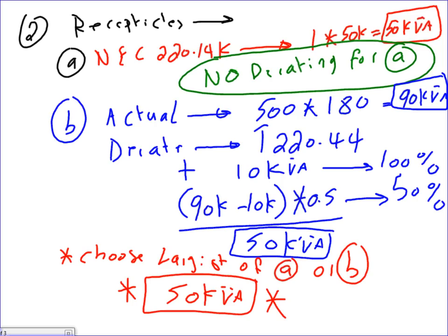But Mike Holt says in his book, for multi-outlet assembly, you multiply, if it's non-simultaneous or simultaneous, 180 VA for every 5 feet if it's non-simultaneously used, or 180 VA for every 1 foot if it's simultaneously used. But I can't emphasize enough, you're going to add them right in here and demand them. Okay, any questions about the receptacles? Straightforward receptacles.